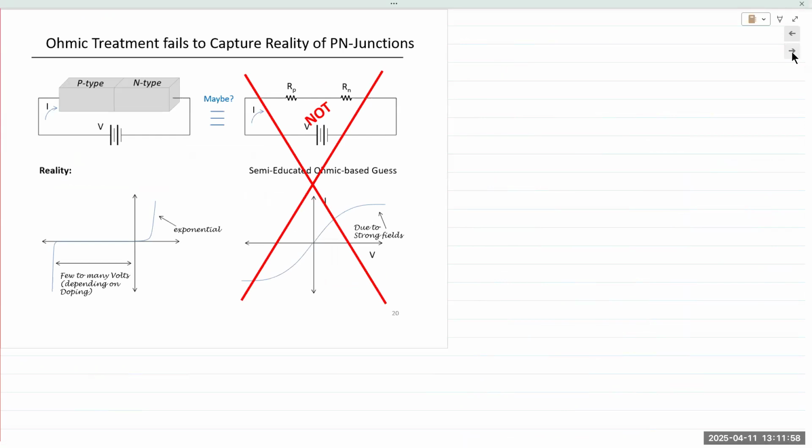So far we learned that we have intrinsic semiconductors that have a certain amount of charge carriers present inherently or intrinsically due to thermal energy. Then we introduce external electrons or holes by adding impurity dopants to our semiconductor material. Because of that, the number of charge carriers is now in such sufficient numbers that we can control the flow of these charge carriers. But overall, no matter what type of semiconductor we have, electrically speaking, it is charge neutral, right? So we have a P-type material and an N-type material. By itself, it's not of much use except in certain applications.